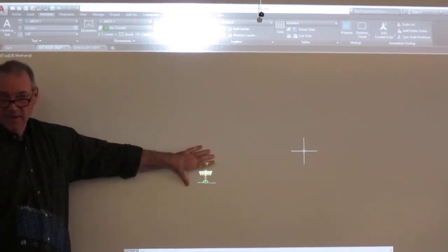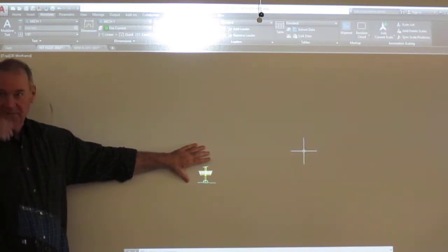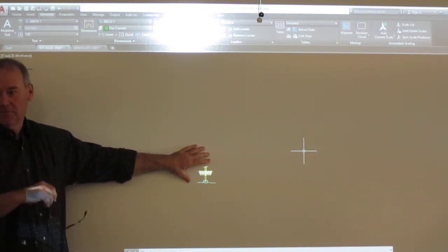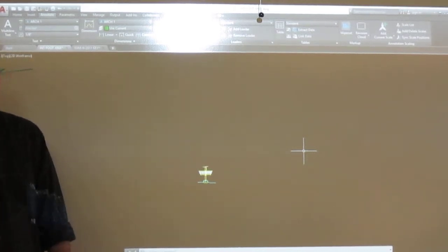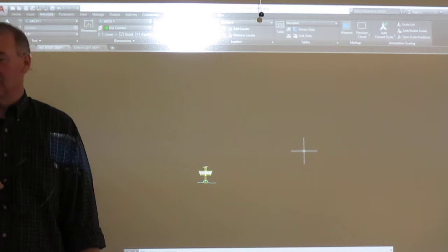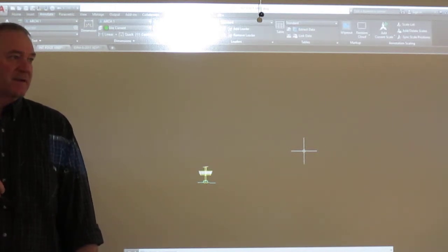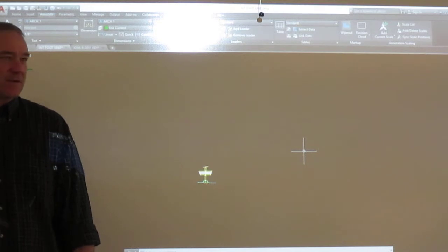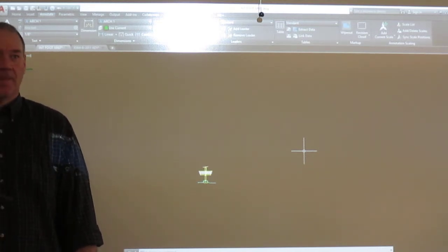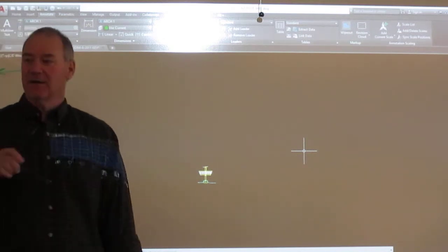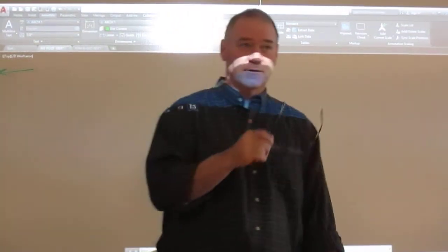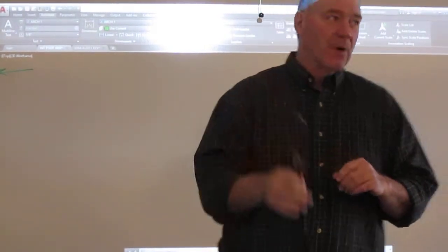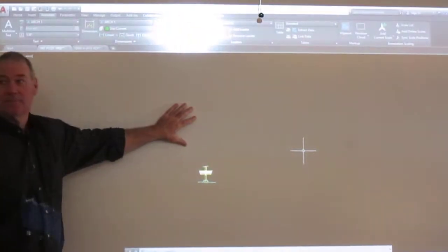Do not dimension it. Draw it at 1:1. Are there any questions on how to get the information off of the print I gave you? Because not everything's sized on here. Things are called out like 1 1/8 floor joists, 2x4s. You can use your architectural scale at the 3/4 scale to measure anything on that drawing. Draw it 1:1 in here, architectural units.